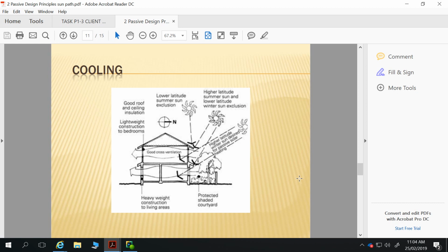But certainly things like awnings and blinds and curtains: if you specify them for your energy rating, it means you've got to put them into the house. Because if you don't end up putting them in, then that energy rating doesn't apply and the building is non-compliant.